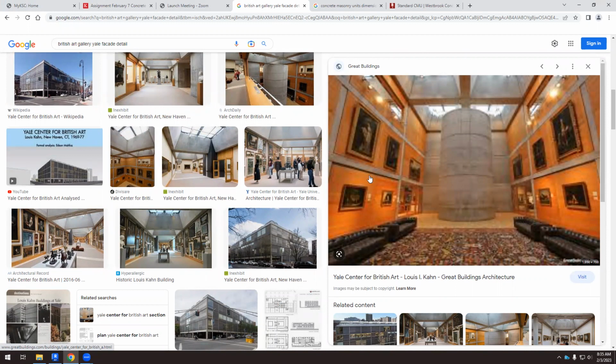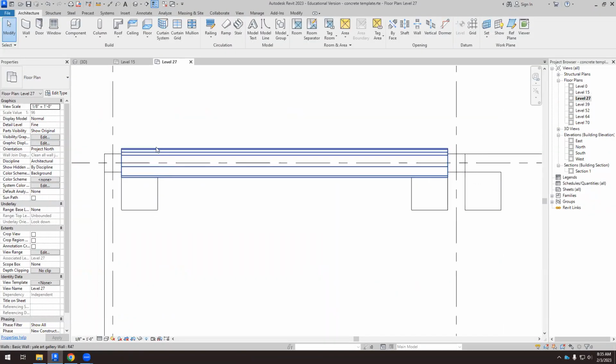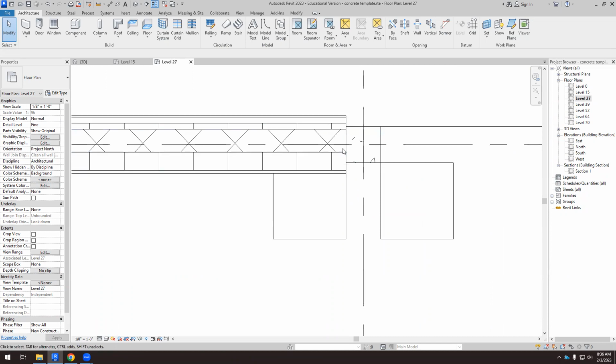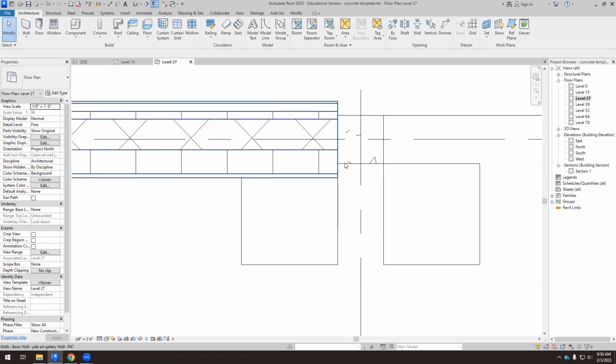doesn't turn over in his grave, but I'm not going to do this. Okay, so I'm going to hide this exposed concrete indoors for the sake of energy efficiency. Okay, because if I do this here, we will have a wonderful thermal breach. Thermal breach is when we interrupt the thermal insulation, and that will give us a lot of problems. Okay, so I'm going to cover this with thermal insulation, with 6 inches of thermal insulation, which I think will be more than enough.